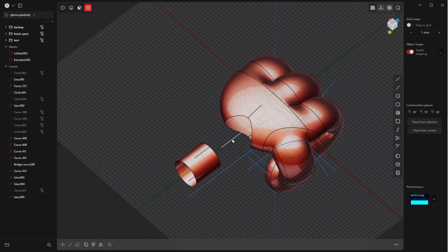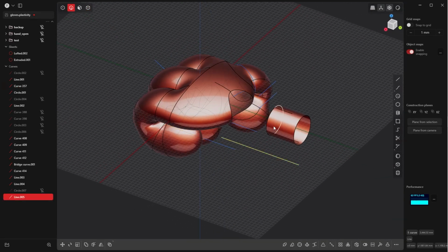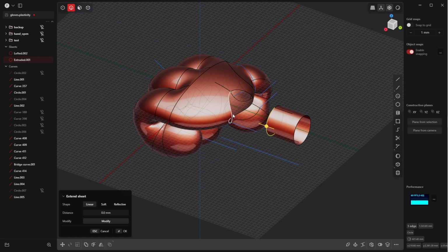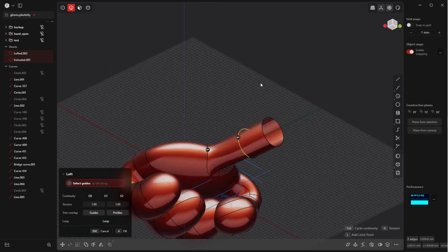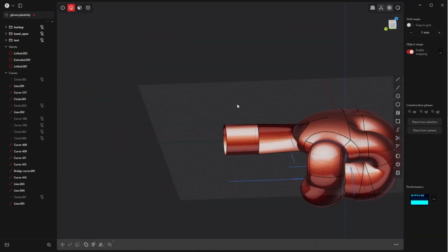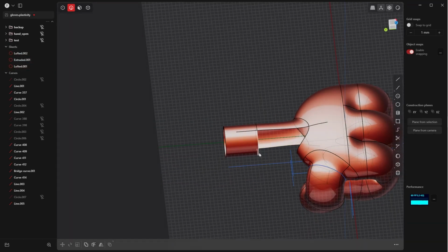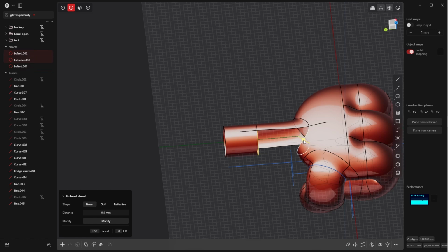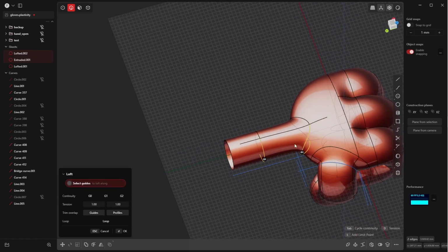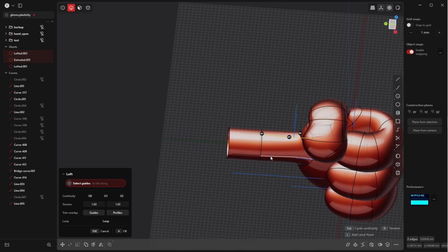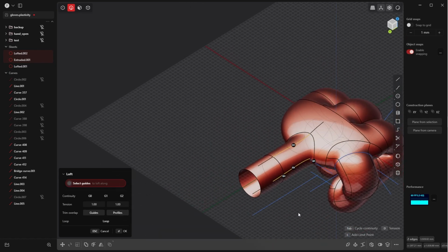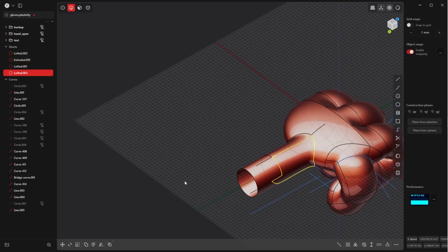And if we try to surface it now, let's see if we still get weird results. So let's first select this half, press L. Yeah, this looks cool. Select these two lines, loft them, and select the edges with G1 continuity. That's okay.